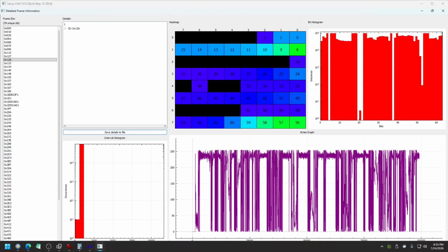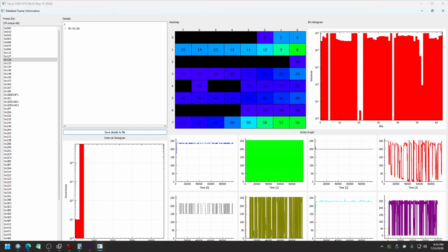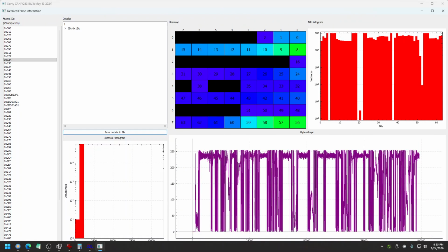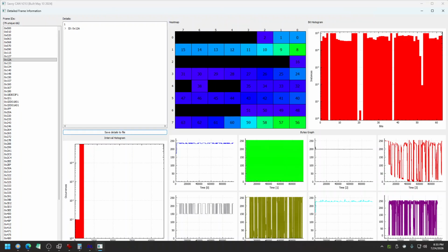And again, I have already looked at this. I already know, this one does the same. This one doesn't start at 0, but it becomes active with the key on event right here. And that's something that you could go back and look at the flow view and try to figure out. But I know that this looks like RPM. This looks like the engine speed signal.